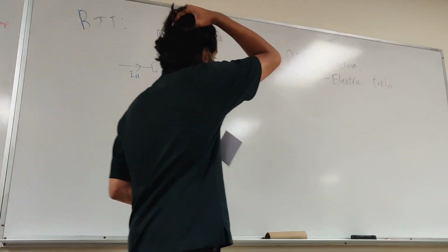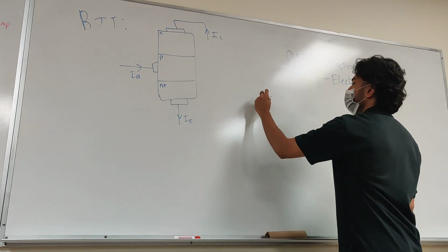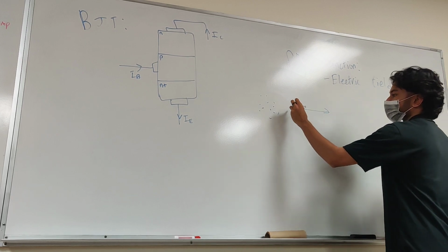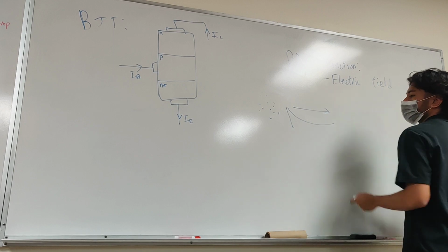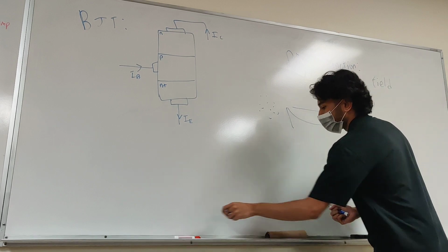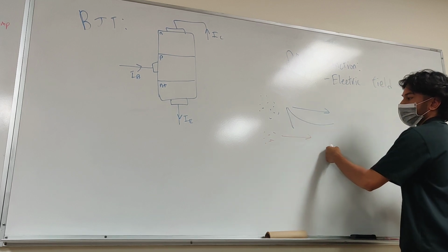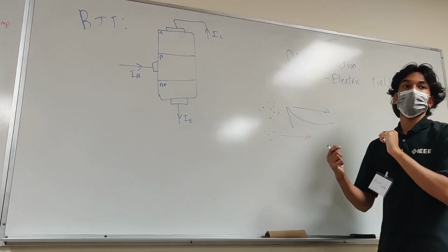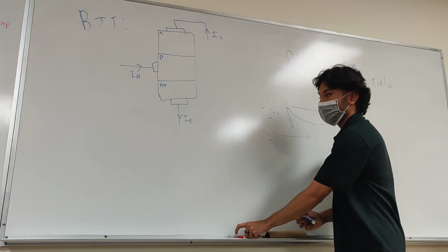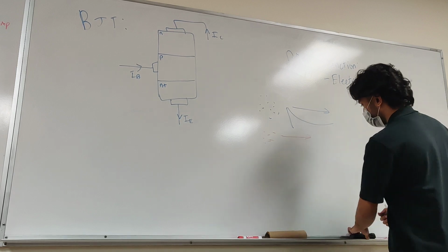Okay. In a BJT, let's say, in a diffusive model, we have a bunch of electrons here. They're going to move kind of this way, right? They're going to spread out this profile, okay? But electrons and holes will not always diffuse in opposite directions. My holes can also move this way. If my holes move this way, my electrons move this way, their currents are not going to add up anymore. Versus in the electric field, their currents do add up. So this is something the BJT employs, this kind of subtracting of the two currents based on their concentrations, okay?